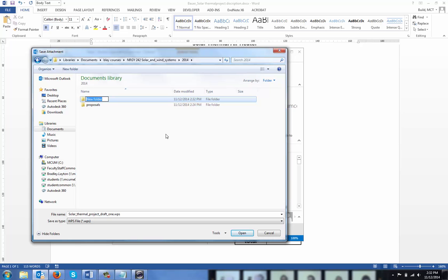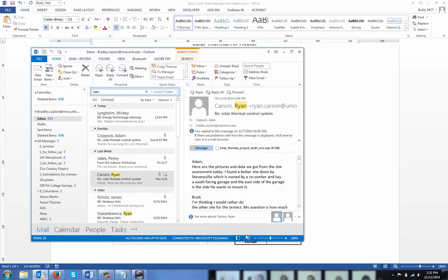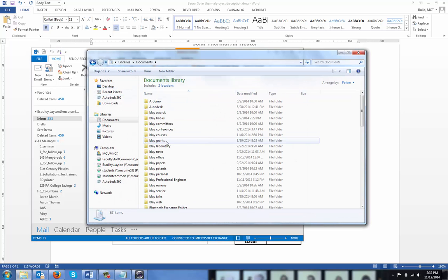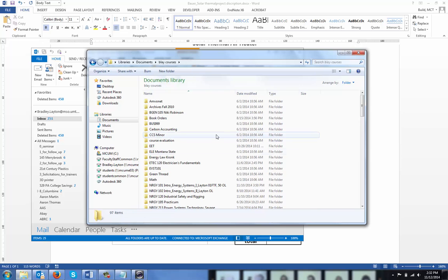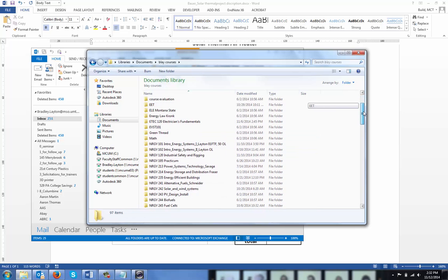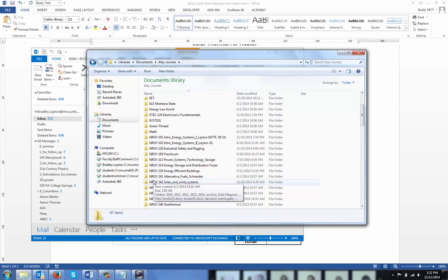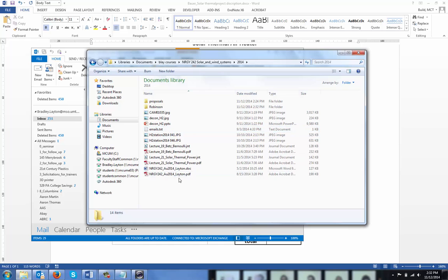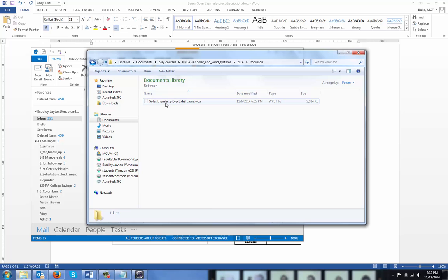Why would you go water and not air? Because I could put that on the roof and pump it. Gotcha. And there's more mass involved, so it wouldn't take as long to heat up, right? Well, it'd take longer to heat up, but it would hold heat better. The advantage is you're running a quarter horsepower pump instead of 120 volt. You'd have to have a pretty monster fan to get any heat out of that solar thermal panel to move hot air.